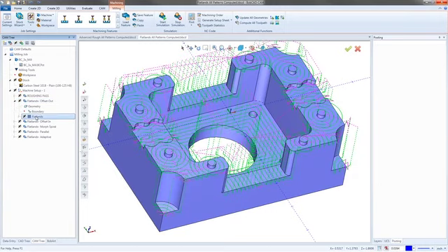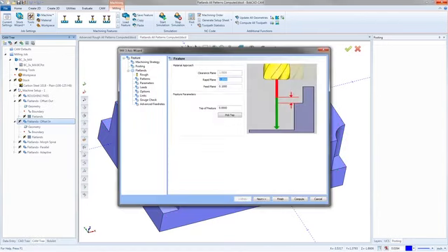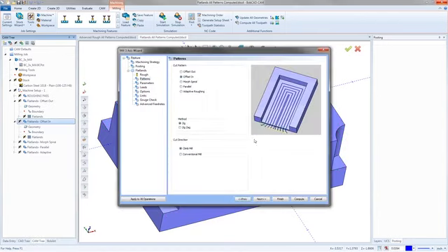So here's the offset out. It's going to start from the inside of every one of these pockets and work its way out. The offset pocket in is going to work its way from the inside. Whoops. That's not the right one. Give me a second. Let me edit this. That's a pocket in. All right.